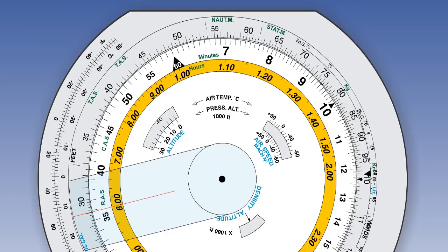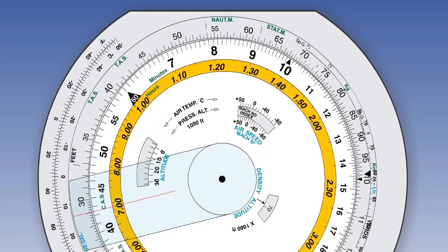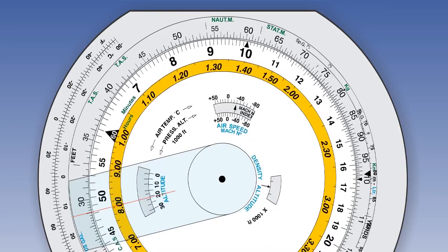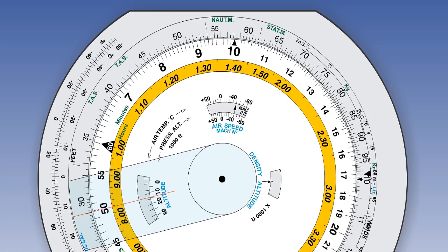Using the CRP5 navigation computer, or similar, and using the same air temperature of -50 degrees Celsius that we used for the formula calculation, find the airspeed window on the navigation computer. Turn the inner scale around until an arrow marked Mach number index appears in the window, and place this arrow against the air temperature of -50 degrees Celsius on the air temperature scale.